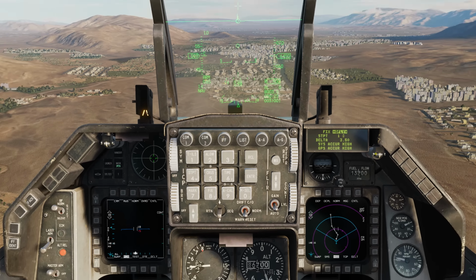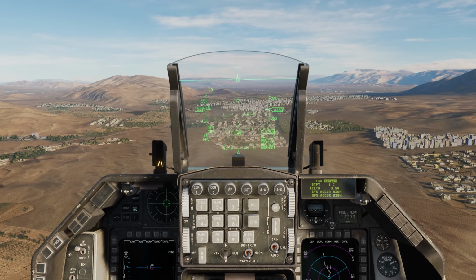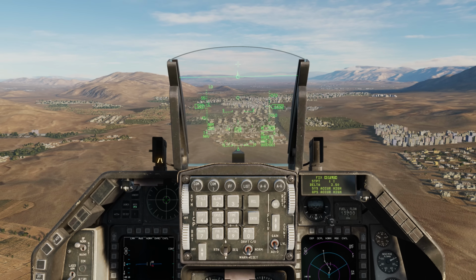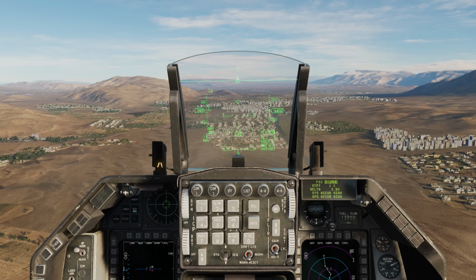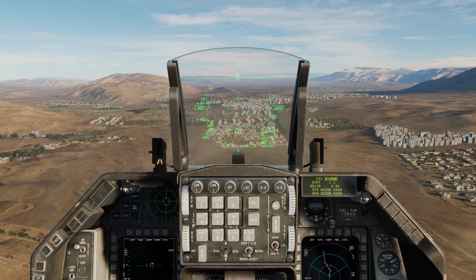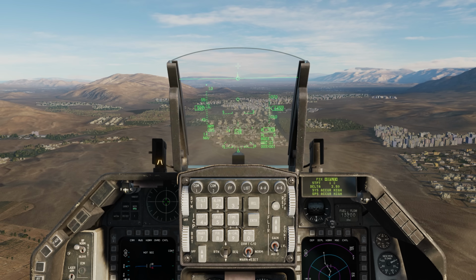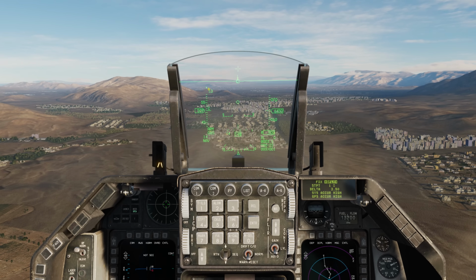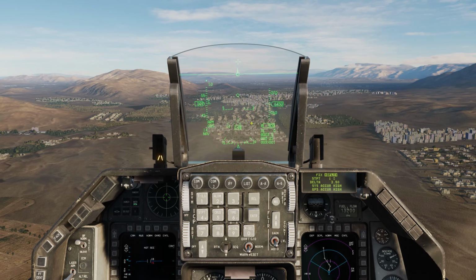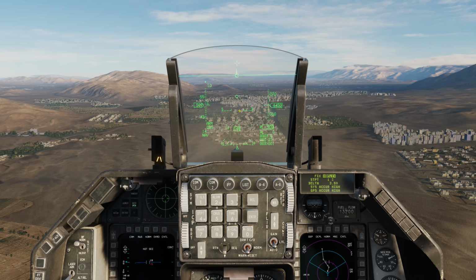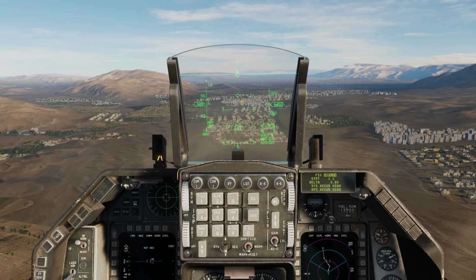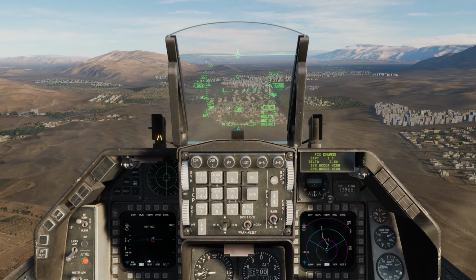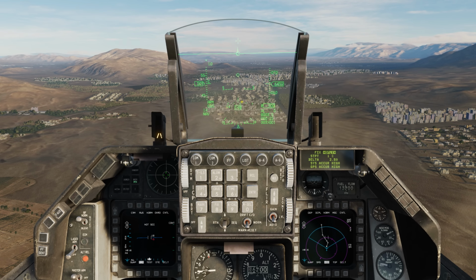this mission. Up on the HUD, we're going to make that our sensor of interest, or SOI, and to do that we're going to go up on the display management switch, or DMS switch. And we can see that with the asterisk up here in the corner. And now I'm going to unpause, and I'm going to first fly past this first indication, this diamond, which is the current location that we believe steer point 1 is.